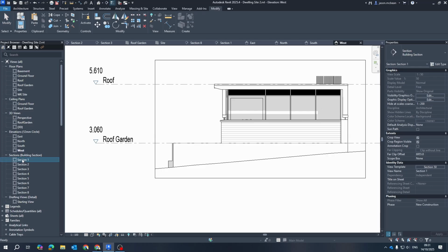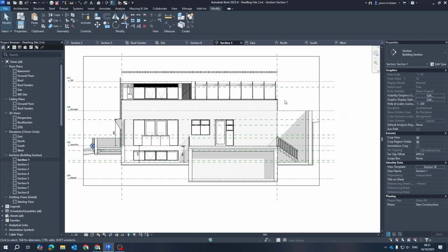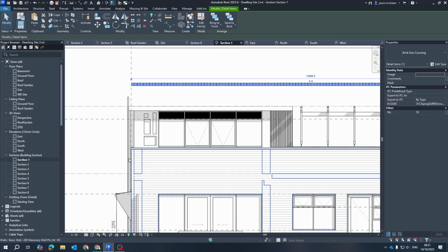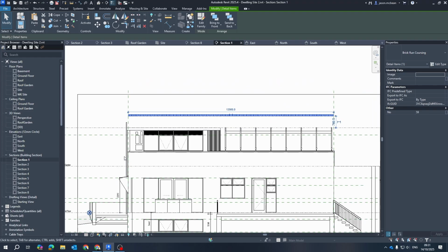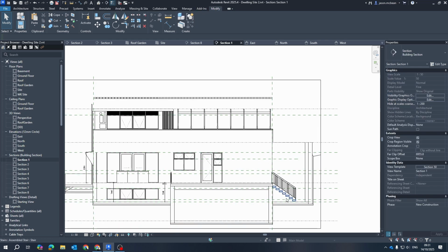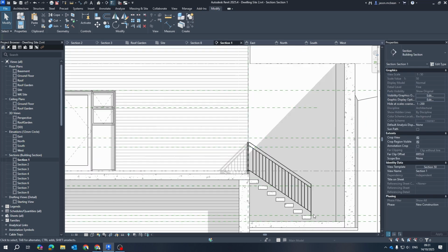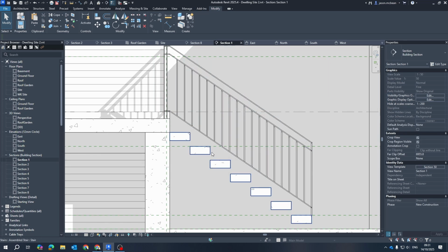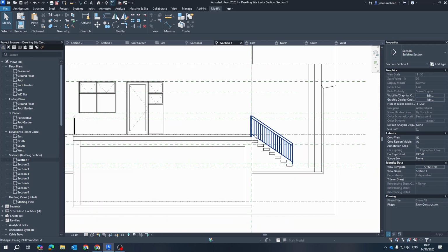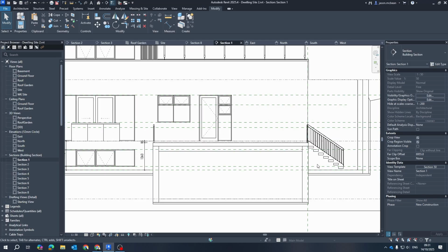In my section views, I've kept some of the information, like the brick coursing. So this whole building is brick coursed. So everything worked with the brick dimension because a lot of it is brick and concrete. I'm combining the two. I've got some floating stairs, for example. Okay, and this is what I mean with handrails. To put all the little connections on, it's so difficult because it's depending on mats. So sometimes we model those things in afterwards. Again, it takes a lot of time.